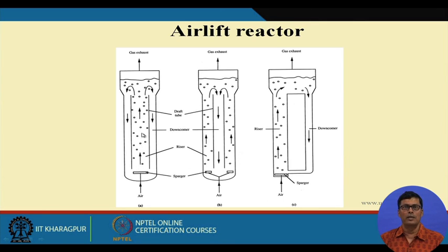You can have the aeration pattern of different types. These are the different internal modes that we have. We can have the aeration here, and then the air bubbles will come here by the dragging force, and this is the external circulation system that we have, through which some air bubbles recycle back into the liquid again, so that the mass transfer in the system increases.